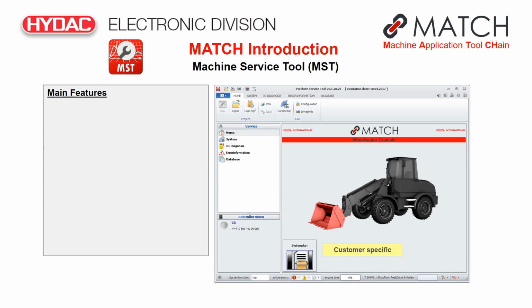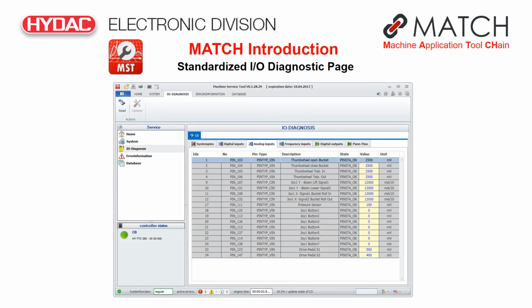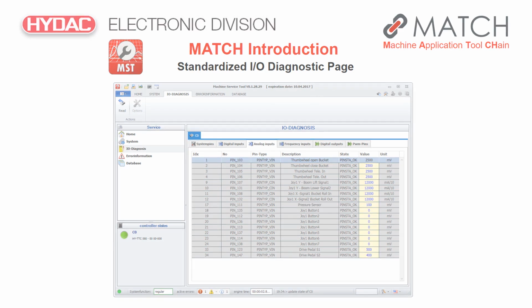The main features of the MST are hardware and software information, non-volatile memory parameter access, error list access, input-output diagnostics, support of commissioning tests, customization features, access levels and languages, standard I/O diagnostic page. This screenshot shows a typical I/O diagnostic page. Details include pin number, pin type, short description, and also the state, value, and unit of those pins.